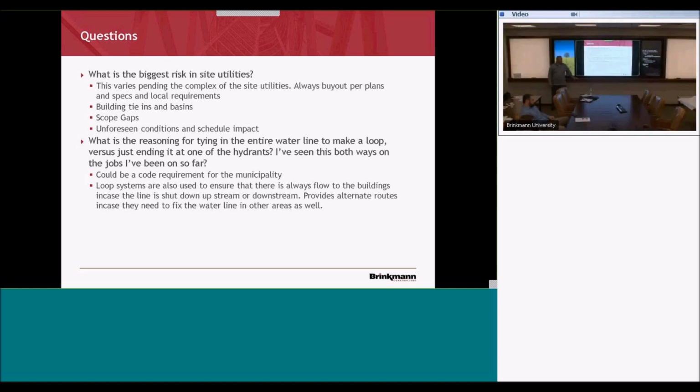On the drawings of Town and Country, the power pole looks like it's 10 to 15 feet away from the building corner. However, on site, you have the pole, and then you have the arms that actually hold the wires. Those arms reach out about 3 feet either side, and the roof truss tails stick out from that building corner about 3 feet. So the distance is deceiving on our drawings versus what actually occurred in the field.